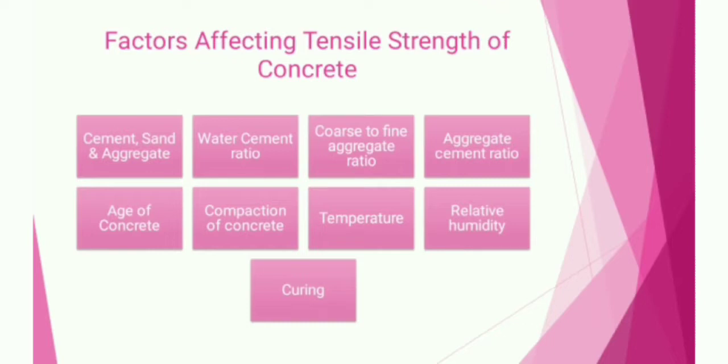Temperature. If the temperature increases, the reaction also increases. This means that concrete kept at higher temperature will gain strength more quickly than a similar concrete kept at lower temperature. Relative humidity. If the concrete is allowed to dry out, the hydration reaction will stop. Hydration reaction cannot proceed without moisture.